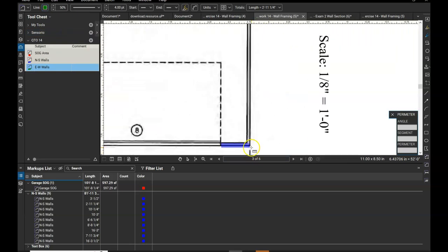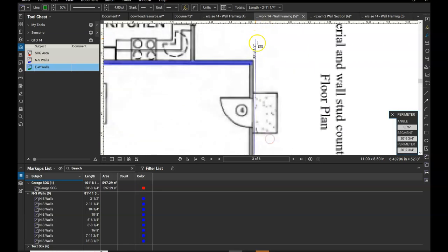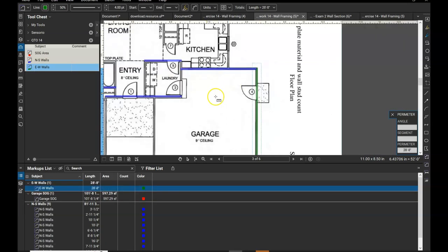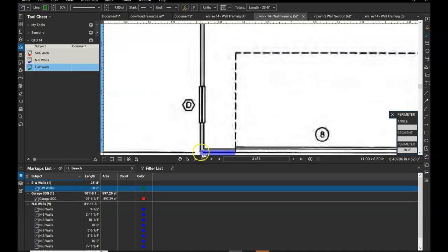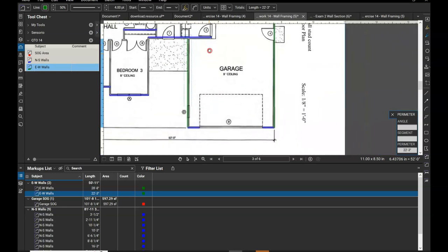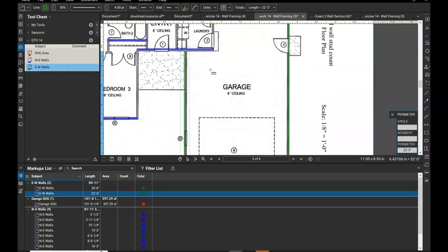And from here, we're just going to keep on going. I'm going to do a few of them. Yep, just go ahead and overlap them. This is, again, a takeoff. So if I were doing this as a framer, just FYI, I would tell my team exactly how to estimate it, and then at the very end, when I'm converting it into Excel or whatever I'm using, I may apply a factor, saying okay, waste factor is another 10, 15%, but if I know I'm overlapping, I may drop that percentage down a little bit.